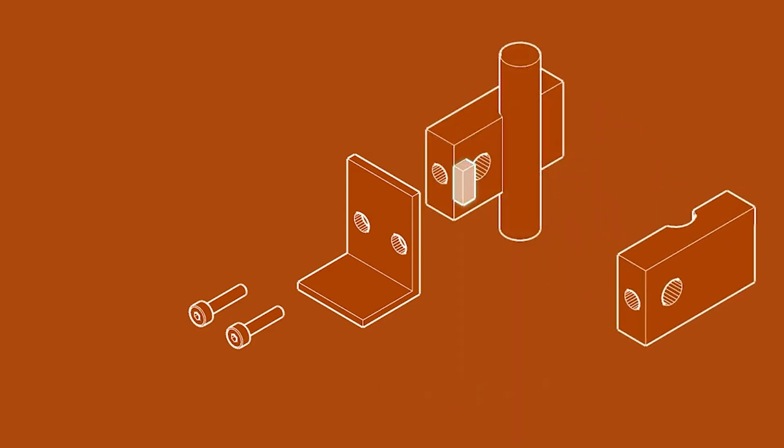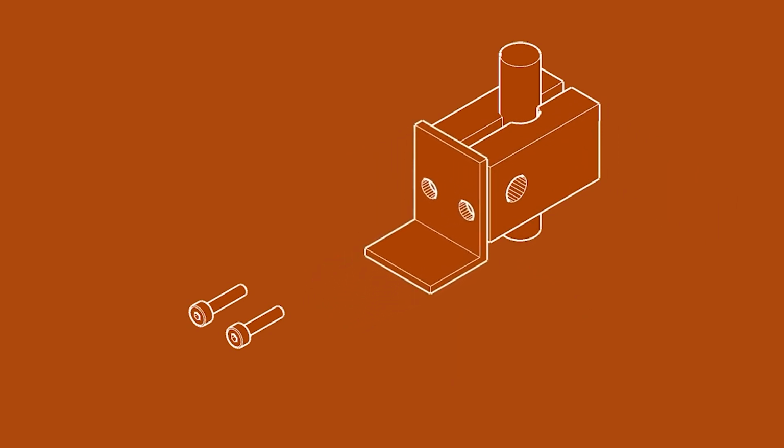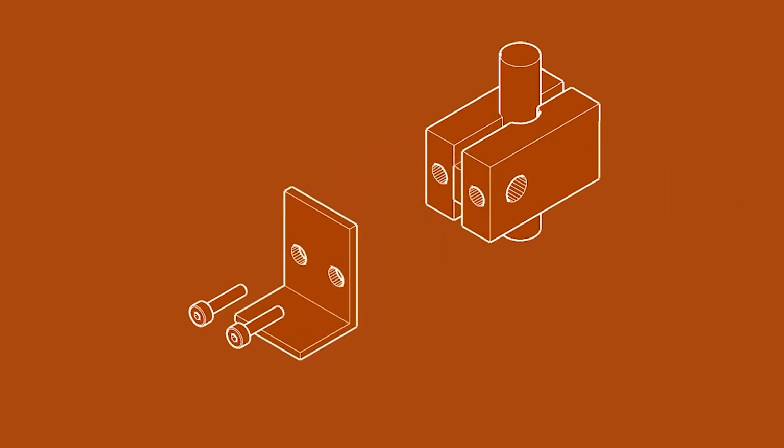So if your pivot is a plane, there is a brass pivot. So if I open that, I see that there is a plane here. Then what I can do is I can put two screws here, and I can attach that to the bracket, and I can use this screw to tighten it. The only thing that you have to ensure is that this is not a full circle. So if I take a block and make a through hole, and if I cut it into two, and if I put it together, then I'm not going to clamp anything. It's going to support each other, no. So therefore I have to take a thin portion out of it so that it can do this. And then I can tighten, and it goes and clamps the object.